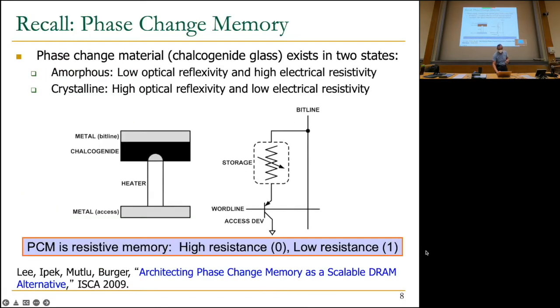Okay, we also talked about phase change memory. Even though it's an old technology, it's new to the main memory domain, let's say, and the storage domain. It was used in rewritable CDs, but more recent works showed that you could use it for main memory as well as solid state disks. So this is actually disrupting the memory hierarchy as we know it today, after such a long time. For a very long time, memory hierarchy was SRAM, DRAM, hard disks, tape. Now SSDs came along, that was disruptive also. And then maybe phase change memory can disrupt the hierarchy again. Right? Okay, we're going to go back even further later.